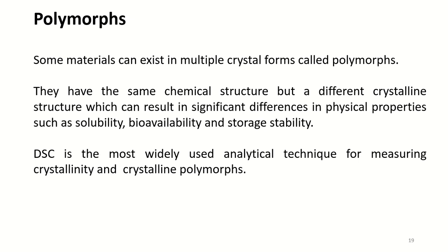Differential scanning calorimetry is believed to be the most widely used analytical technique for measuring crystallinity and crystalline polymorphs. However, the results are often misinterpreted by some users who fail to realize that the sample may be changing as it is heated.